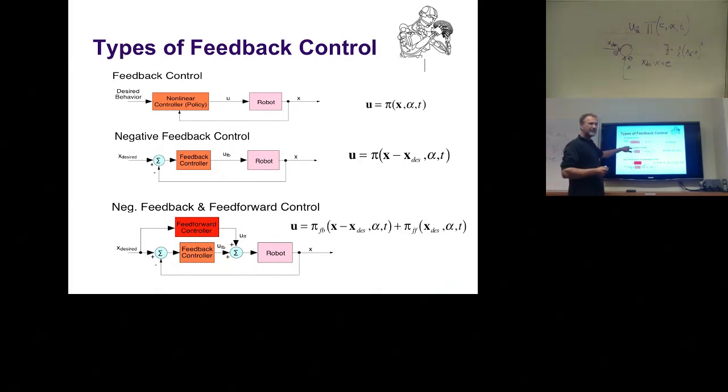So what this is good for is if you have a desired trajectory and you need to do error correction. And that is what typically happens in a tracking controller. You want to follow a desired trajectory. This desired trajectory changes over time, and you want to basically stay close to it, and basically the feedback controller pushes it towards this desired trajectory.